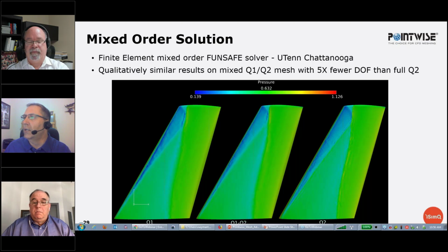Thank you. One for Steve regarding high order curved meshing. What's the maximum order that Pointwise curved meshing supports, and what basis functions are you using for these elements? That's a good question. Pointwise is basically a mesh generation program. So we are dealing with geometry, and we are using Lagrangian basis functions up to polynomial degree 4. So the distribution of the higher order nodes is an equal spacing frame of reference. And this is consistent with traditional textbook type discussions pertaining to higher order.